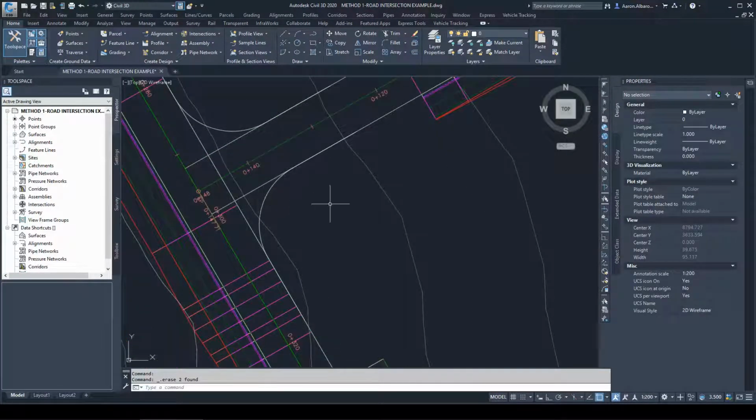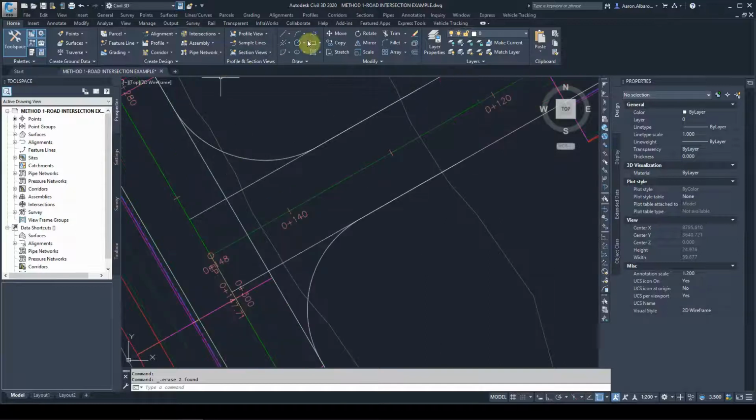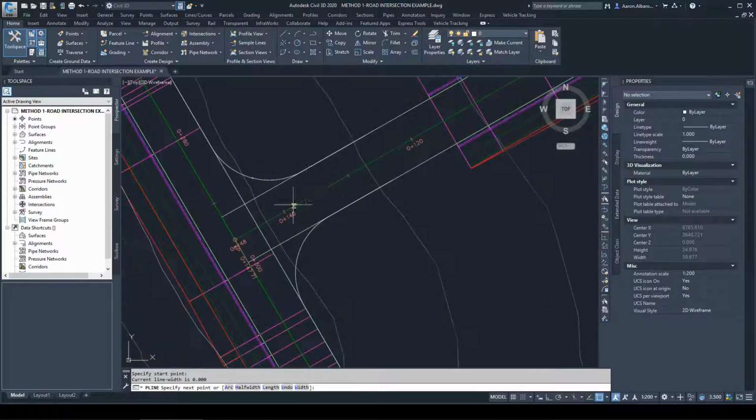And on the outside, obviously, I've got the daylight targeting the existing surface. So the same thing will apply here. If I have a polyline here on the inside where the lane is, I want it to target this line here, because I already have a lane here. I don't want it to be extended all the way. Stop here. And when we get to that point there, I want it to target this line here to create that cross section for that road here, because I already slid that corridor to the back.